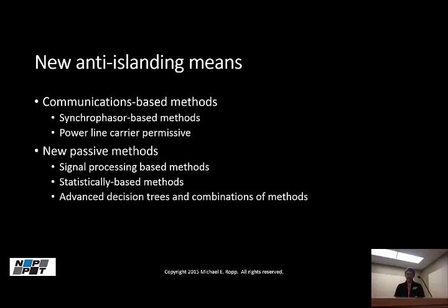And the one that we are using, actually, we're just looking at a statistical correlation between the two frequencies. If we're grid tied, then locally the frequency should track pretty well with the grid because that's a universal parameter, right? It's pretty much across the whole system. As soon as the island forms, the frequency controls, such as they are, are independent in the island versus on the grid, and the correlation goes away. So this method has actually worked extremely, extremely well.